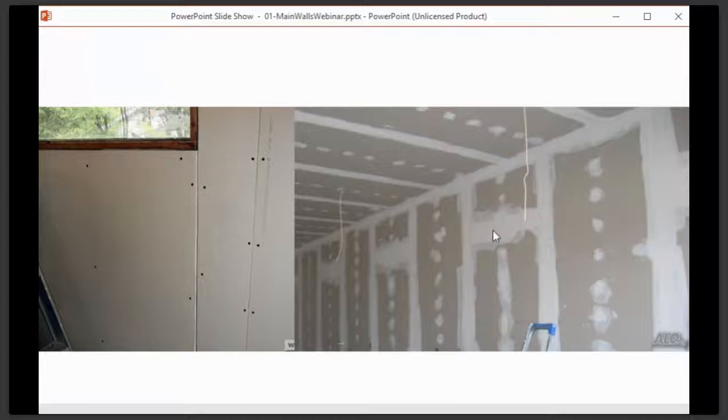Okay. And this is another thing that's worth mentioning at this point as well. If I'm doing something like electrical, and I'm not sure, say, what distance I want the lights to be at, I'll always make sure that they provide me extra wire. I'll specify a meter of this from the ceiling height, because at least then I have the flexibility. Simple things. We'll cover this as we go along, but it's better to have too much than too little.